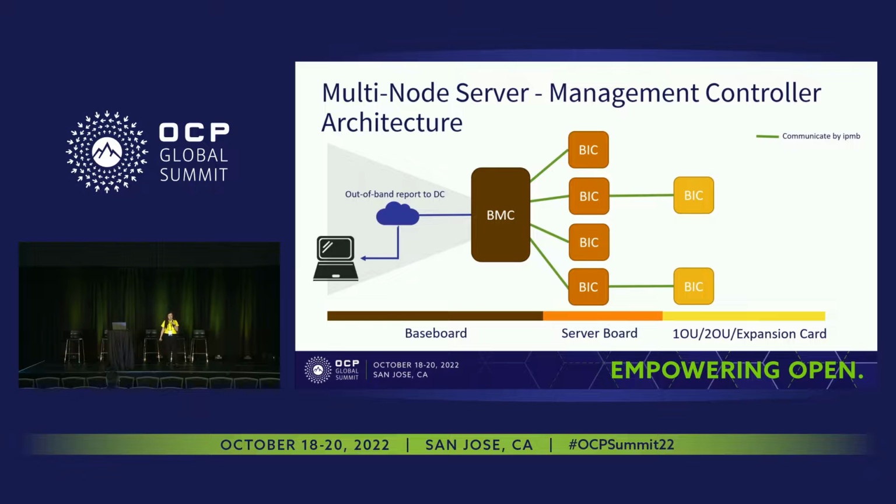Next, let's get started. Overview the management controller architecture. The base board has an OCP NIC card. So BMC obtains its network access through the OCP NIC card by NCSI connection. So the end user can communicate with BMC through the network. We provide different kinds of user interface, such as IPMI out-of-band command, REST API, and some SSH command.